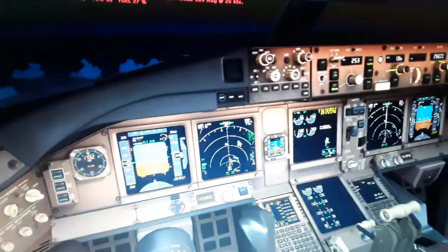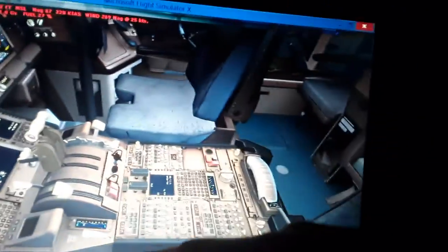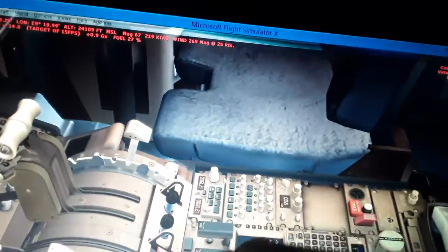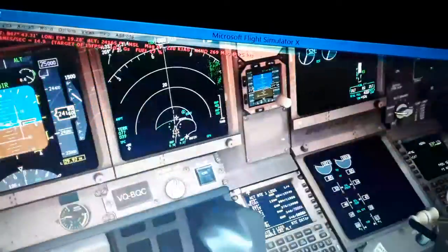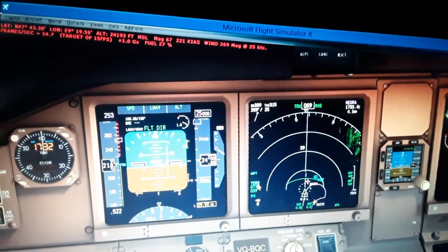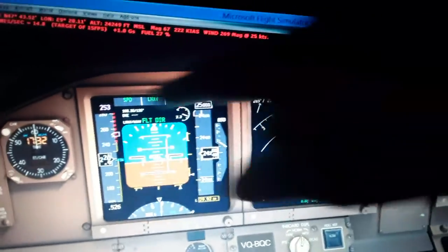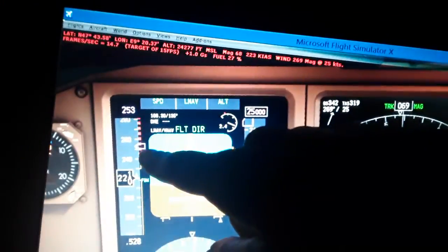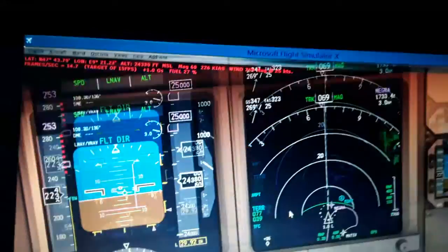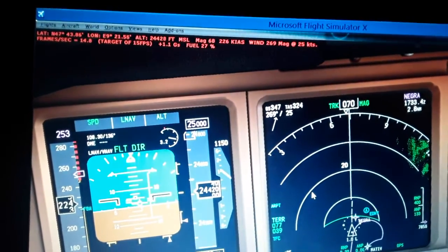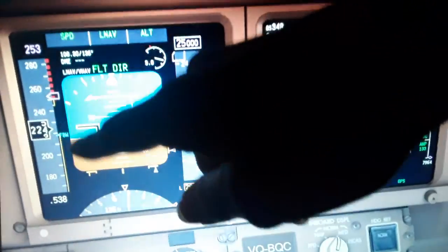Climbing a little bit higher, maybe retract some flaps. Now we don't need so many flaps, so this is going to increase our airspeed to a higher level. You can see the flap setting here, flap limit moving forward, so retract the flaps one more time. We're going to have higher airspeed margin. So you can see also the stall margin here.